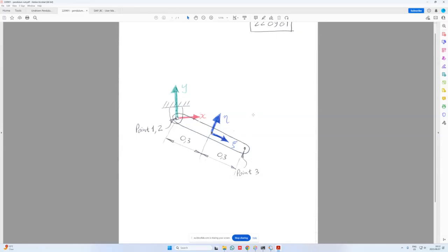We know that it's not actually going to swing up to there, but we essentially just want to specify a bound that is large enough to accommodate 0.6 meters on both sides. So in the X direction, I can use minus 0.6 to 0.6, or I can go a bit bigger. In this case, I'll make it minus 1 to 1.